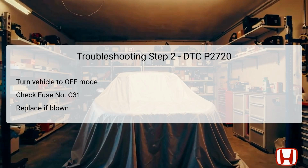Moving to the second troubleshooting step for DTC P2720, the technician needs to turn the vehicle to the off-lock mode first. After that, checking fuse number C31, which is rated at 7.5 amperes and located in the underdash fuse/relay box, is crucial. If the fuse is found to be functional, the technician should proceed to the next step.